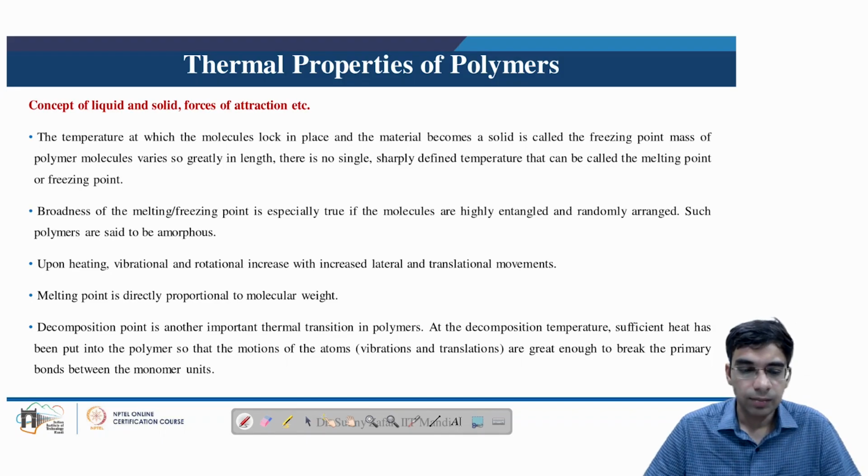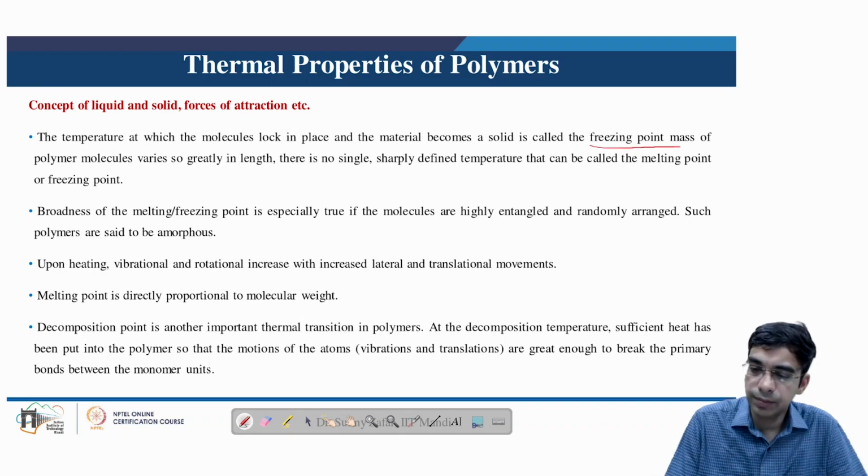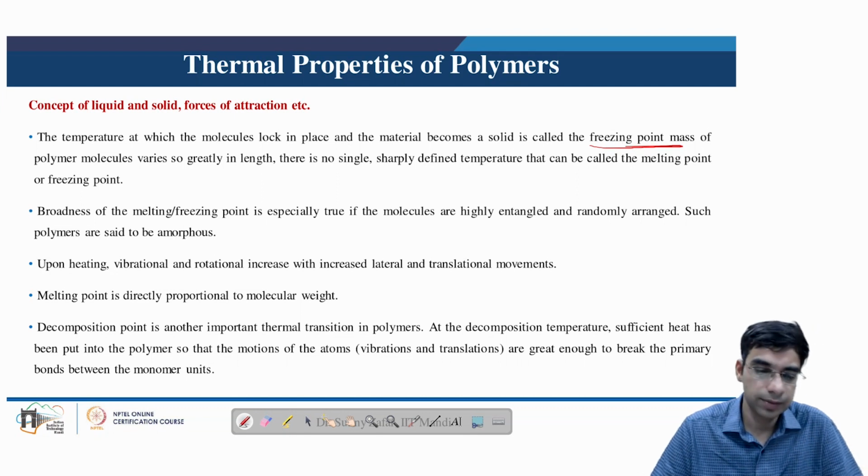So if we look at the thermal properties of the polymer, in this case we will look at how the concept of liquid and solid is applicable in polymers and how the forces of attraction at the molecular level function in polymeric molecules. The temperature at which the molecules lock in place and the material becomes solid is known as the freezing point of the polymer molecules.